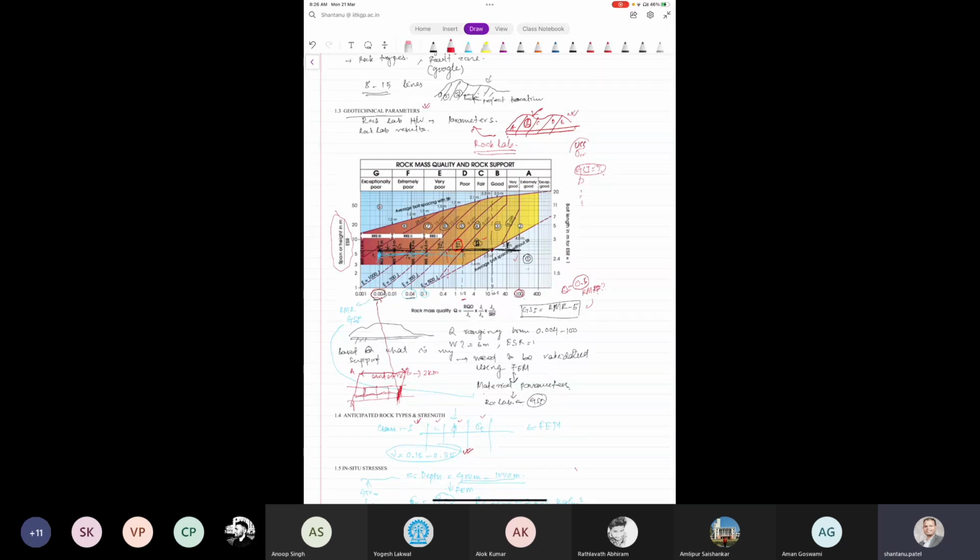But another structural discontinuity is here, but maybe it is not that huge, or maybe the damage in rock is a little bit less. So that can form somewhere in the next zone of class, like maybe it will be in class 5. So within the same rock itself, if you consider your rock mass parameter, that will change. The intact rock parameter will not change, but even if you consider more sets of joints, because of the tectonic activity, as a whole the rock parameter changes.